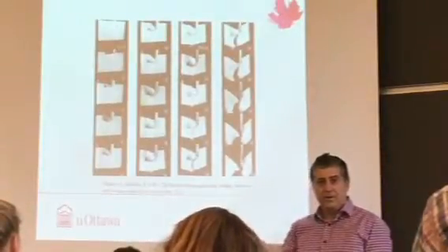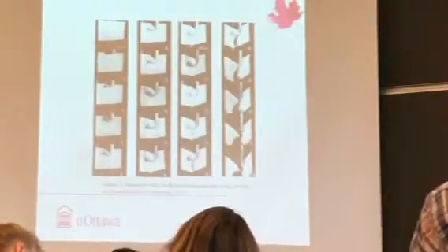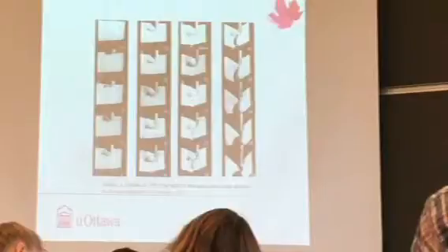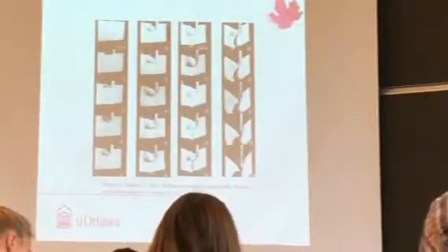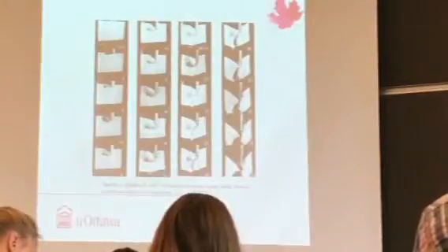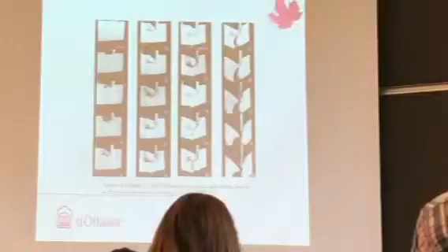Some of you have. So if you take a beam and you load it in timber, do you know how roughly it breaks most of the time? So you initiate a failure somewhere, let's say we have a knot here, some sort of a defect. So you initiate a failure here. And then because wood is weaker along the shear line in this direction, it propagates this way, and then it hits maybe another knot that's stiff and it cannot continue. So it comes back again and it goes like this, and maybe it fails, right?